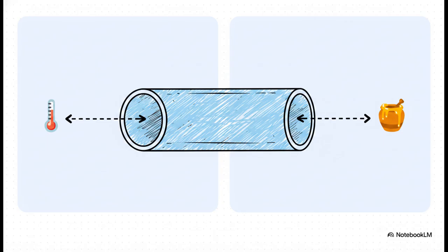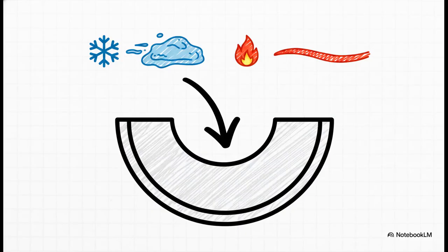As a general rule, you must evaluate properties, like your thermal conductivity, for example, at the bulk mean fluid temperature. That's just the average of the inlet and outlet temperatures. Easy enough, right? But there is one major exception: viscosity. Whatever you do, do not fall into the viscosity trap.